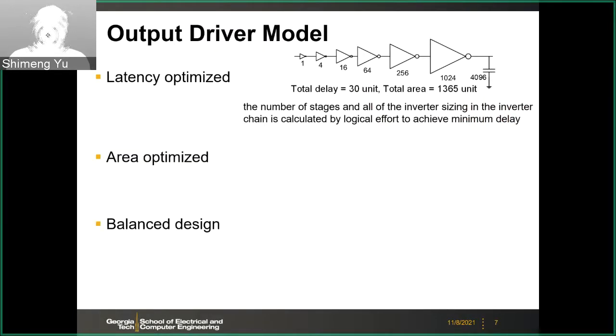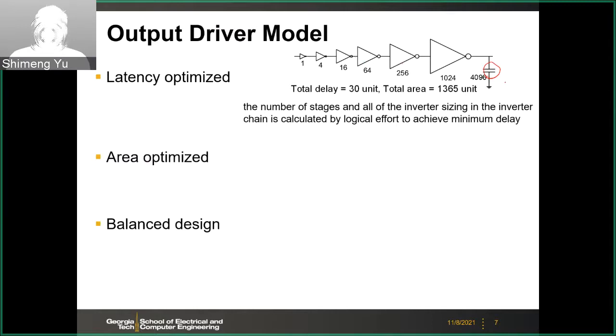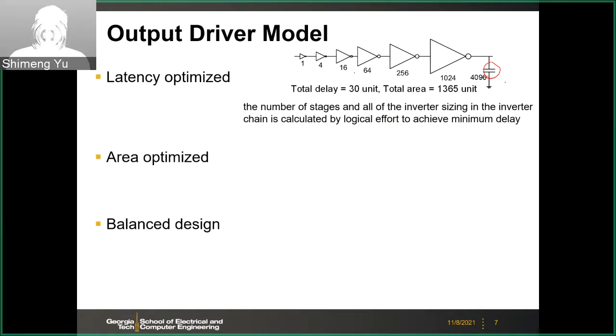So here let's look at some examples of the driver. This is also the content of your VLSI courses. And here, if you want to drive a capacitive load, you can design a stage of inverters, or a chain of inverters. And if you want to optimize the latency, then you have to optimize the number of stages.